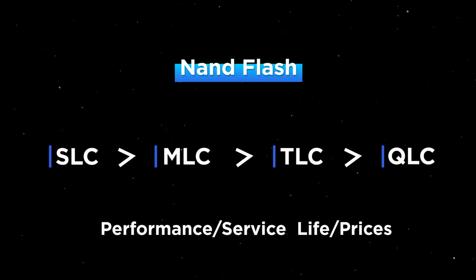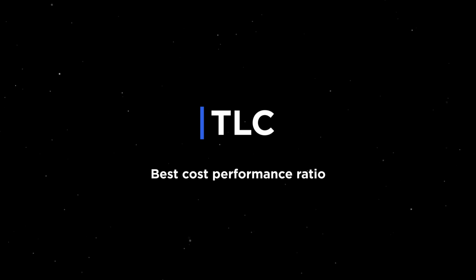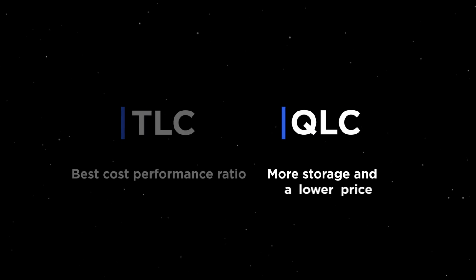As for the performance and service life, SLC is greater than MLC, TLC, and QLC in turn. The prices are in the same order. With the development of flash memory technology, laptop products have changed from HDD to SSD storage. At present, TLC is the mainstream choice of laptops as it delivers the best price-to-performance ratio we have seen. With the improvement of QLC flash memory technology, QLC took off and became more widely accepted, offering consumers more storage space at lower prices.